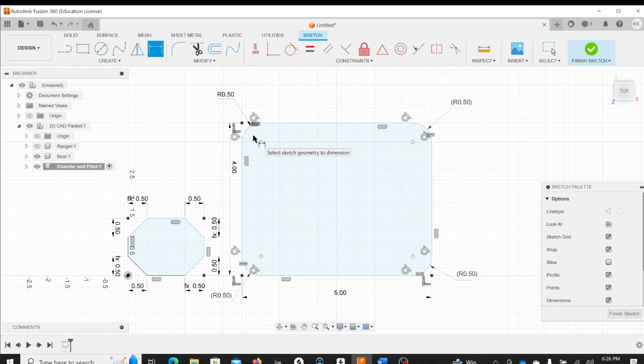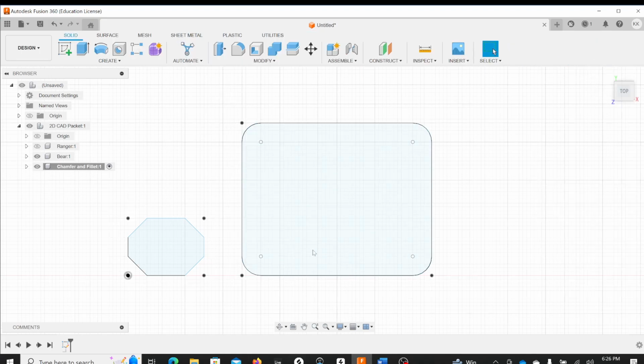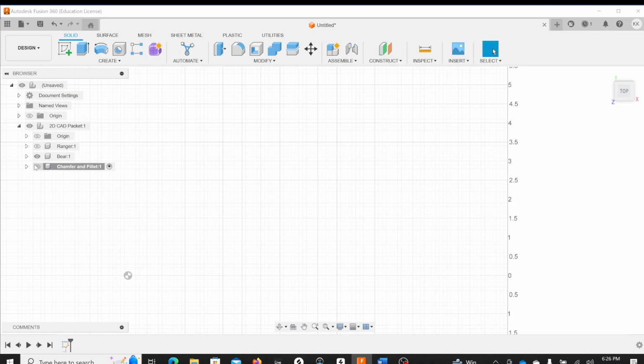So we're going to go through the next model that deals with some chamfers. You already know how to do fillets now, so when you run into that later on, you'll know how to tackle that issue. But we'll run through the next model called Bear that deals with chamfers. So go ahead, finish sketch. If you followed along with this, you can even turn that off. Come up here, activate component, and if you have not already, create the Bear drawing or the Bear component where we will make the drawing. So I'll see you in the next video. That is how you chamfer and fillet corners.